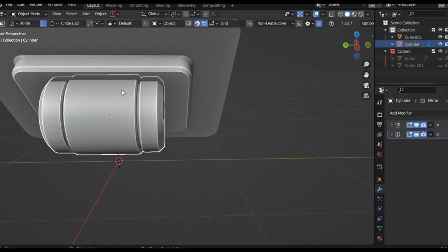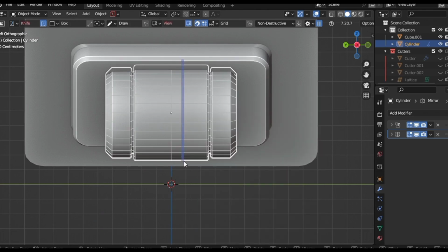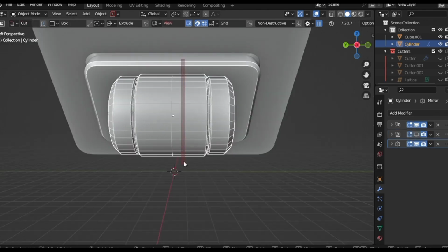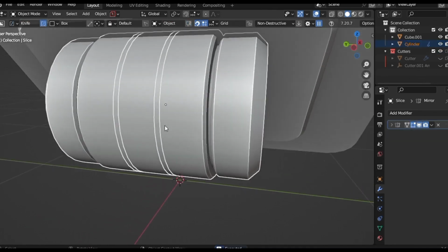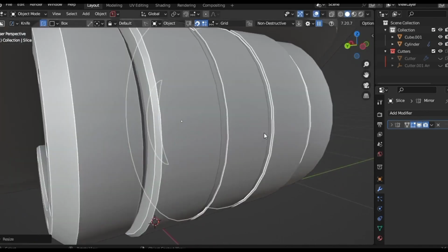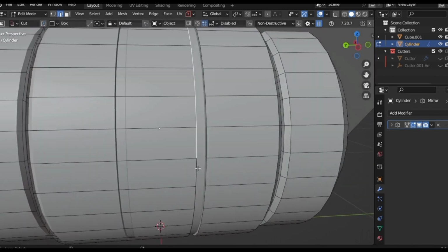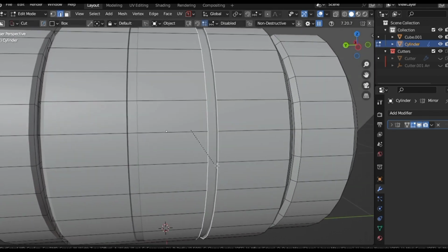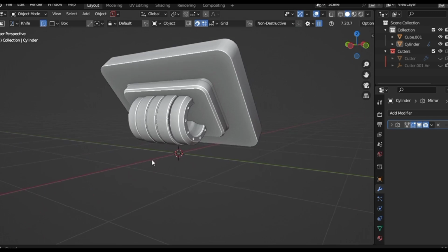Now, moving to the back. I'll cut a rectangle in this area and E for extrusion and X for slice mode. Selecting this new piece, I'll scale it down slightly to reveal more detail. To enhance the highlight, I'll select these two edges and apply a tiny chamfer. Looks epic. Now let's structure the screen.